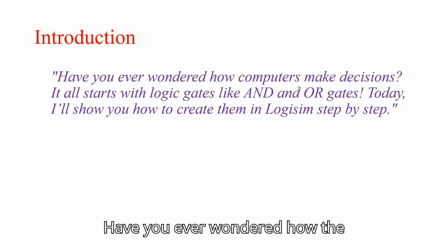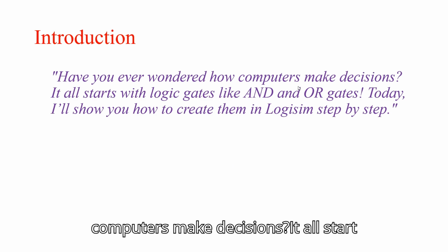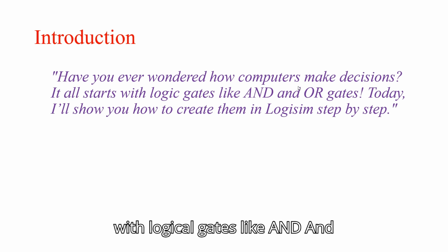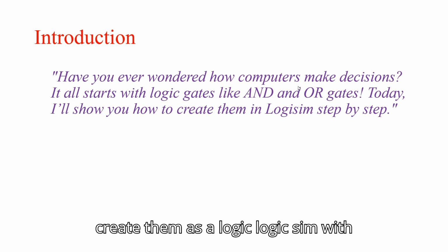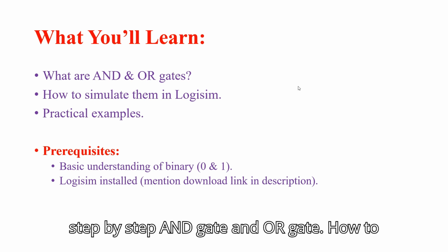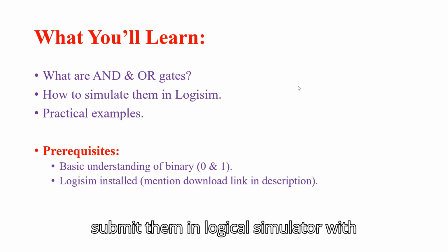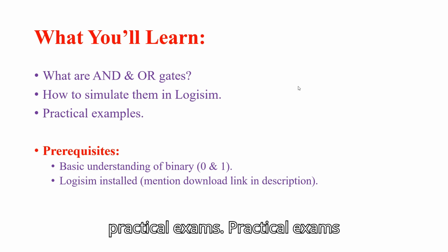Have you ever wondered how computers make decisions? It all starts with logic gates like AND and OR gates. Today I will show how to create them in Logisim step by step: the AND gate and the OR gate, and how to simulate them in the logic simulator with practical examples.